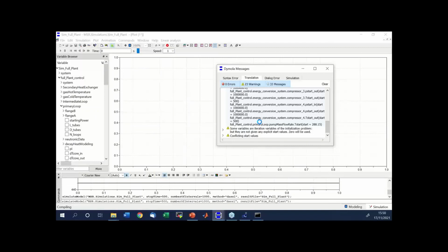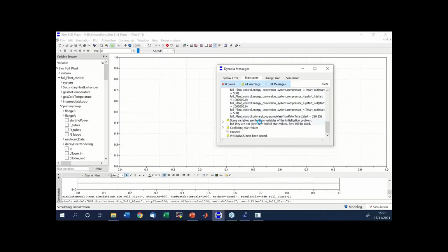What we are going to expect is that our temperature will increase because of the reactivity feedback trying to counterbalance this external reactivity. Since we are inserting positive reactivity, we want negative reactivity, and since MSFR has strongly negative reactivity feedback, we'll end up with an increase of the average temperature.